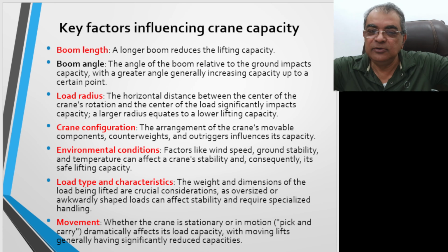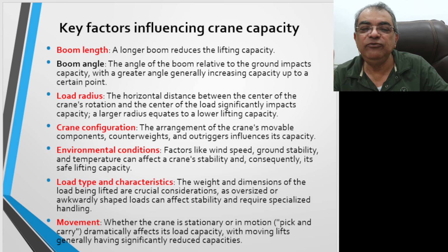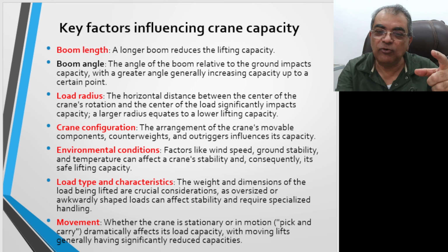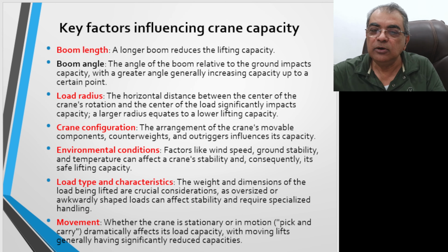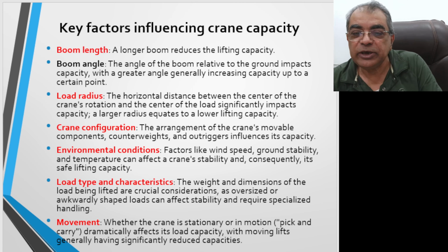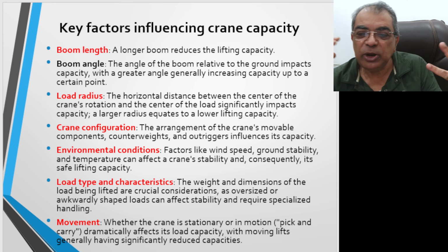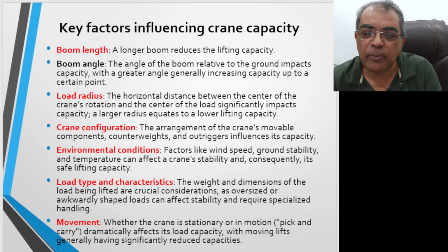Load radius, as I have explained, is the horizontal distance between the center of the crane rotation and the center of gravity of the load, and it significantly impacts capacity. Crane configuration, what type of crane it is. Environmental conditions, wind speed, and the ground stability, as I have explained, and the temperature can affect the crane's stability and consequently its safe lifting capacity.